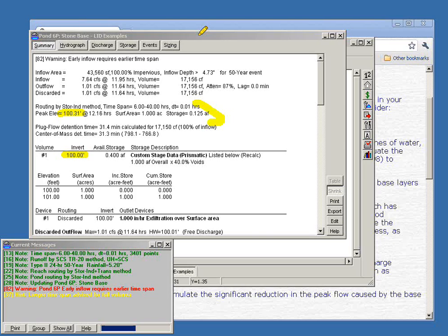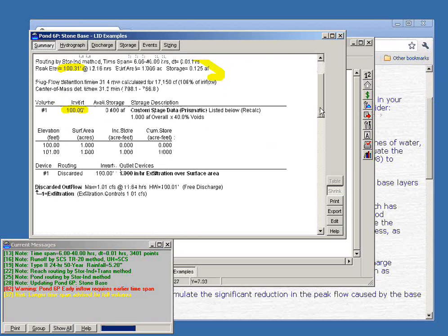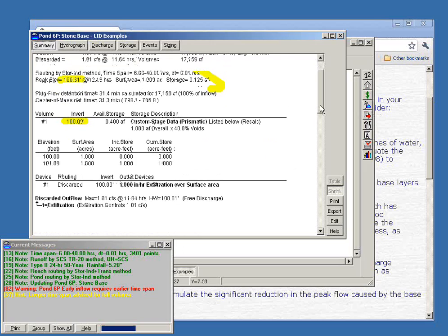And then you would still be discharging it perhaps through an underdrain or via infiltration, but the rate at which that occurred would not be a critical element of your design, because you'd be able to retain everything, so you can allow it to infiltrate over a fairly long period of time.